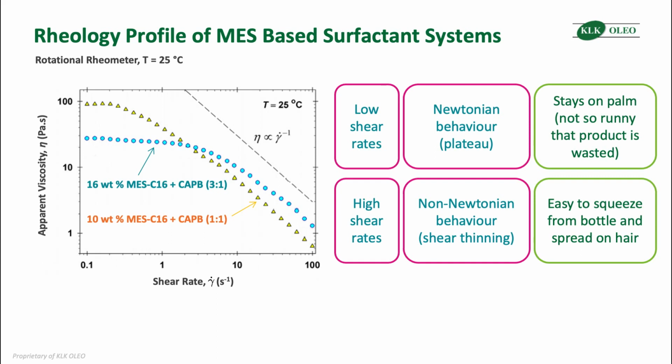This rheology profile is suitable for shampoos. Because we want it to be fairly viscous when it's on our palm, we do not want it to be so runny that it spills onto the floor. But at the same time, we want it to be flowable when we squeeze it from the bottle and when we spread it on our hair.